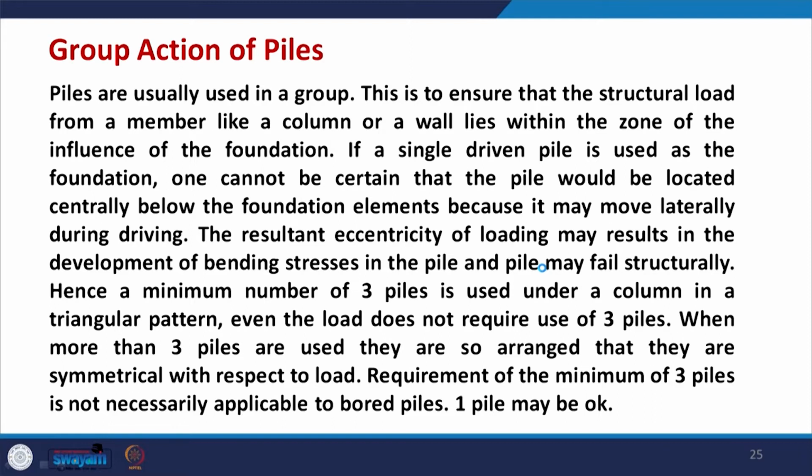When we talk about group action of piles, as said, piles are usually used in a group. This is to ensure that the structural load from a member like a column or a wall lies within the zone of influence of the foundation. It is very important. Suppose your superstructure is there. From the superstructure the load will come through either a column or it could be a pier of a bridge.